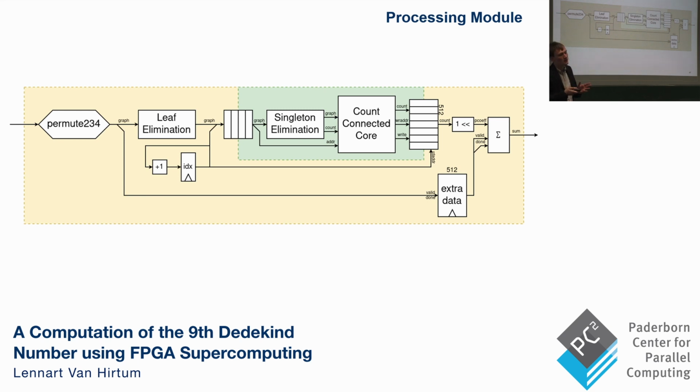And this is really nice about this little loop construct we've got, because FIFOs and memory blocks are both really natural places to perform these clock domain crossings. And so in practice, we found that on the Intel FPGAs that we're using, there is actually a second faster clock that we can use for this one, which runs at about 450 megahertz. And then we leave the rest of the hardware around here at our base 225 megahertz. And so this way, we can optimize the part that really matters, and we don't need to spend too much hardware pipelining all of the other components.